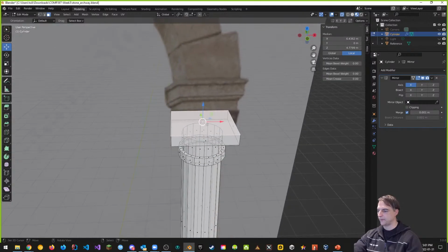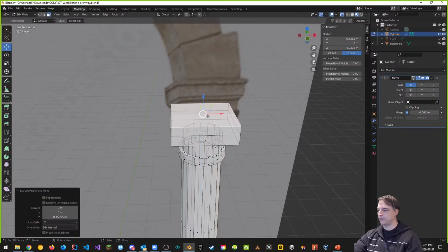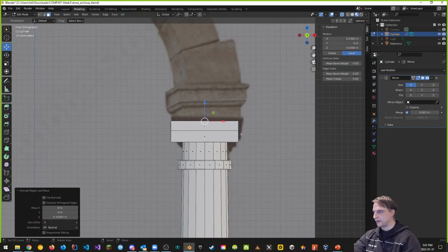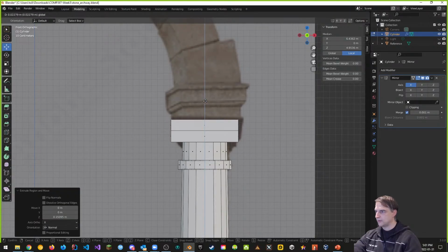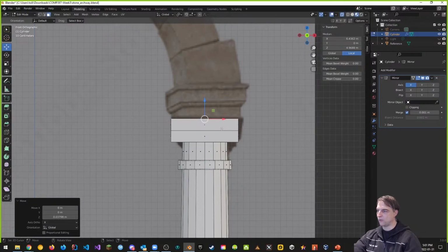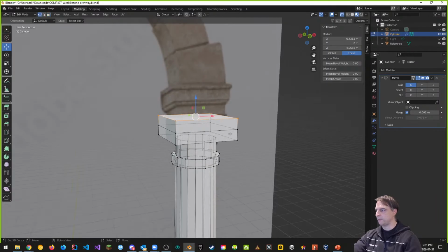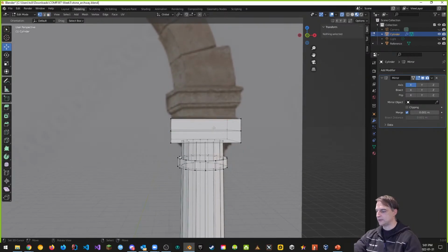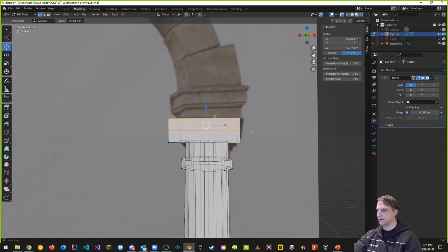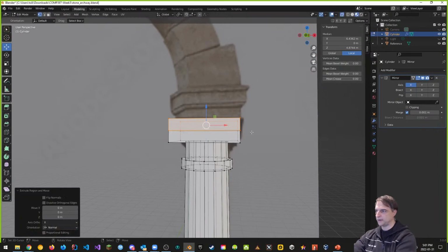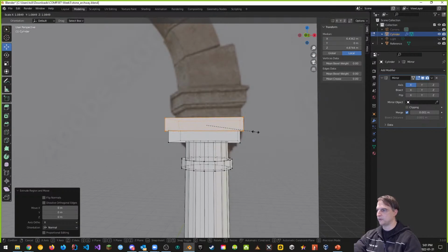So example, you can extrude up and then expand, right? So to make it more of a base. So you can extrude, you want to move that up a little bit. And then what you want to do is, as you look at where that is, let's move that part, let's say up to that point there. And then maybe we make that whole thing an expansion. Now to do that is not that bad, right? So again, vertex select mode is what I would do. And I would deselect all, select only these vertices on the top by keeping the vertices at the bottom unselected. And then I would extrude and then enter and then expand just like normal. So that we do something like this.